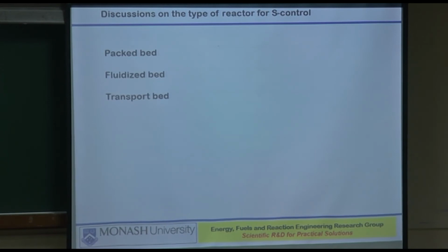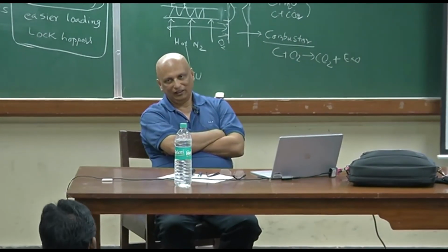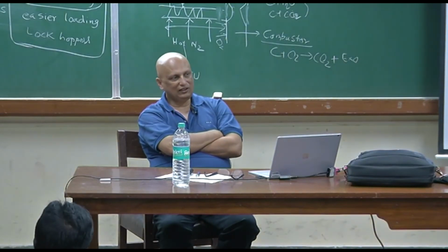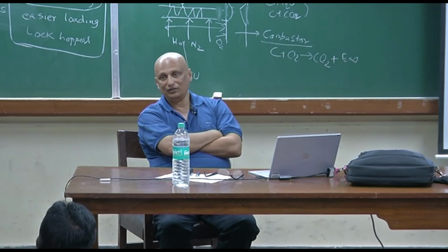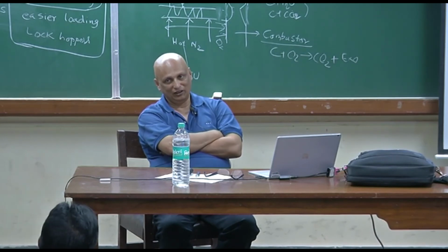When a particular bed goes into standby mode, the reason it goes into standby mode is so that it can be cleaned, relatively easily, and then replenished. So those are physical, mechanical design things. You have to provide the manholes, for example, so that the manholes can be opened, and if required, a person can go inside. If it is a tall and skinny one, it will be difficult to do it that way. So a whole lot of considerations eventually go in.